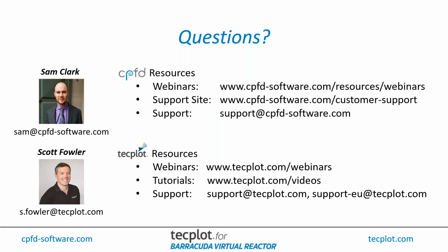Yeah, sure. After you do that extraction, you have the data in Tecplot, and there are a couple of ways you can get that out. You could certainly write the data to a file. We have a couple of ways to write data from Tecplot, so you can get it in a text format. And as Sam alluded to, we do have our Python API, so you can interact with the data directly in Tecplot 360 using Python. We have some very nice APIs that will allow you to query the data live while it's in the Tecplot GUI to get that information out and do further analysis. So I think you have a lot of capability there.